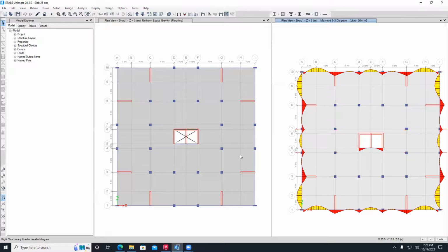That's why the codes ask that when you calculate the moment at this stage, you release the moment and make it equal to zero, and you add also another negative moment on the side. So you design for positive and negative, okay? Because there is some uncertainty here about what's the short. So that's why the design is completely different from the analysis.